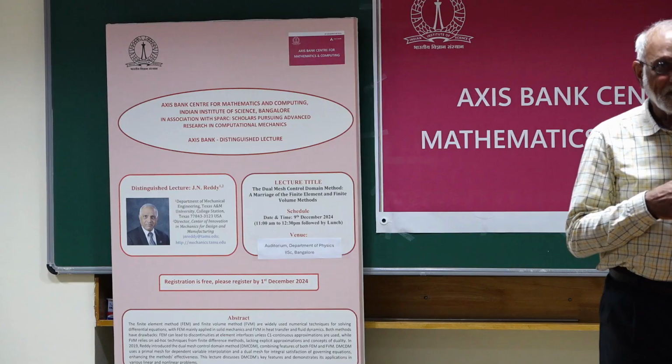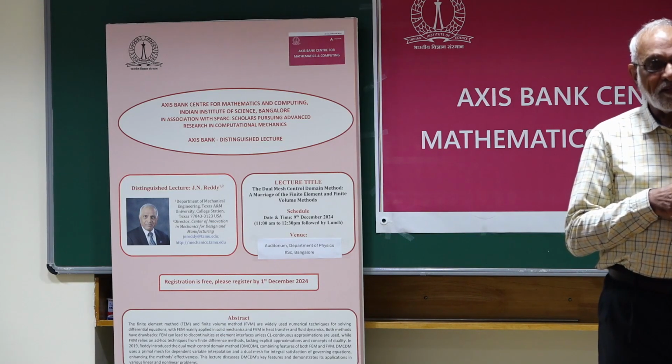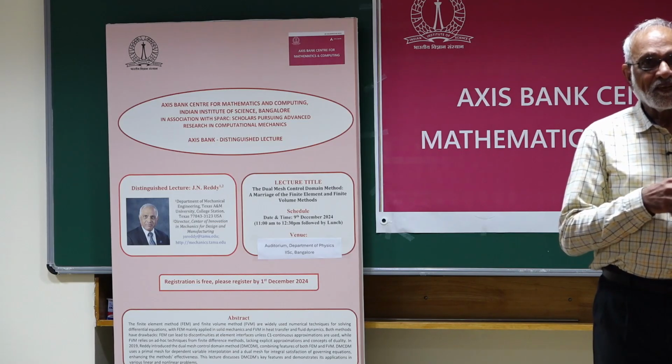Thank you, thank you for a very nice talk. I have two questions. The first one is, I see that this method has some similarity to the discontinuous Galerkin method. Again, in discontinuous Galerkin, at the numerical boundaries, right, you impose fluxes, numerical fluxes like finite volume. To overcome that, people have come up with these flux reconstruction schemes where the numerical fluxes are also modeled based on these interpolating functions, right? So how is your method different from the FR?